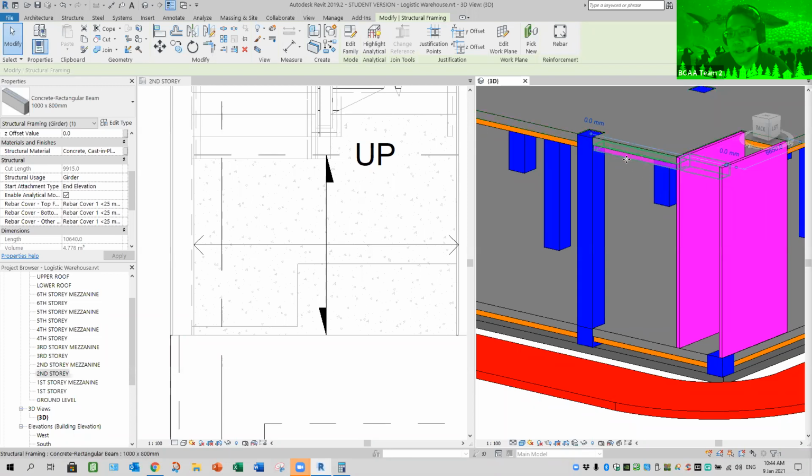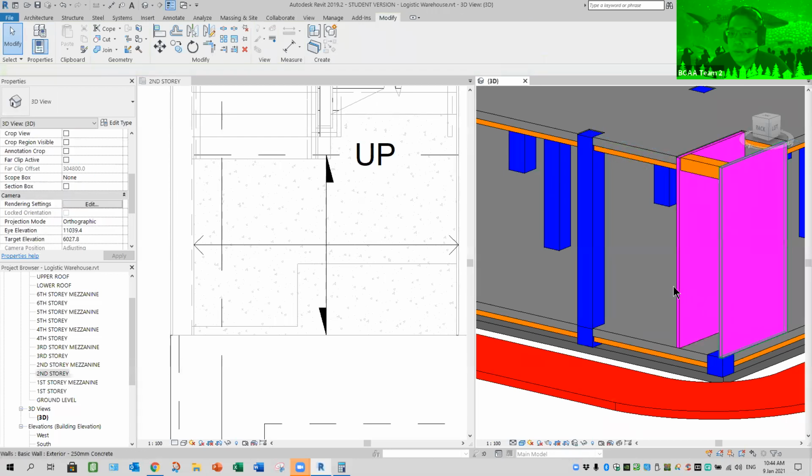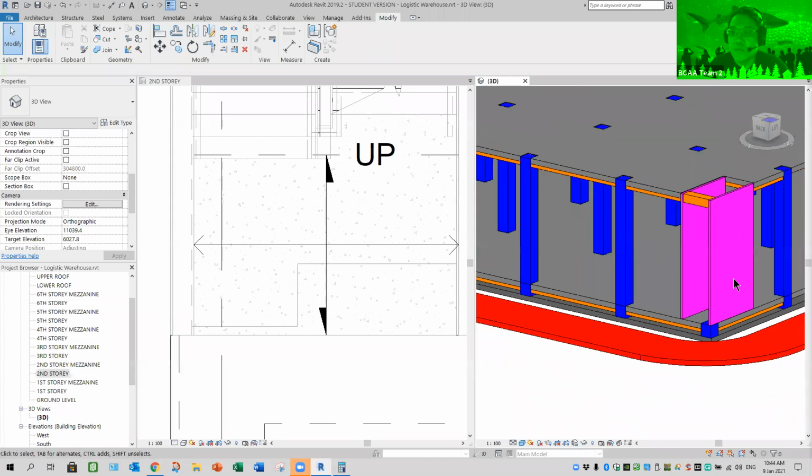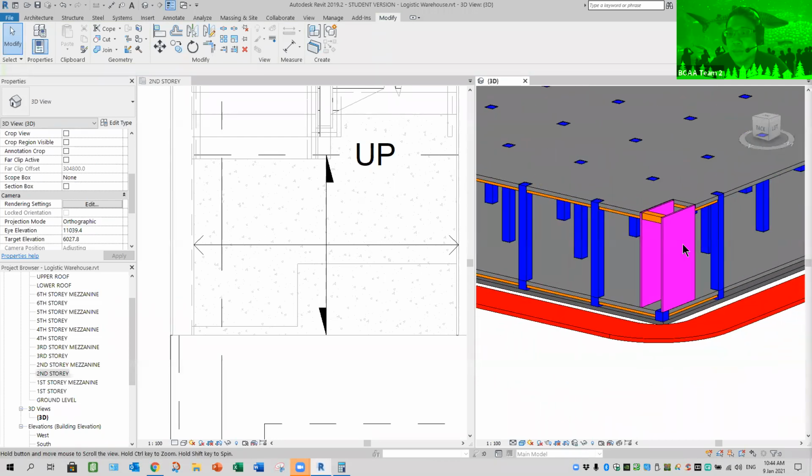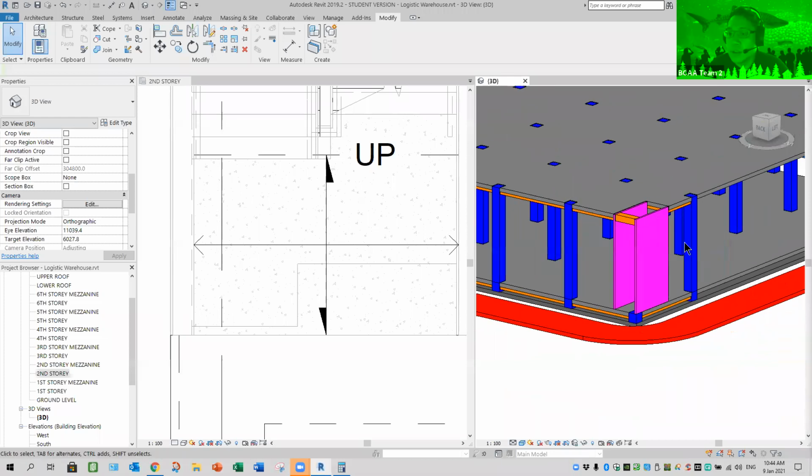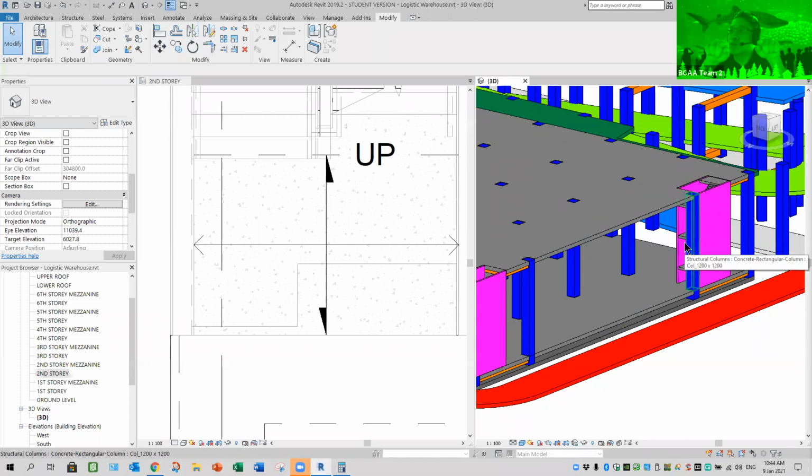All right, because to them it's a break. Okay, but don't affect the original one on top. Just draw a separate one if needed, to get these two walls connected. Also, at the same time, it can act as a support for your landing below if that's needed, because you need to mount your curtain wall, not just on the slab.